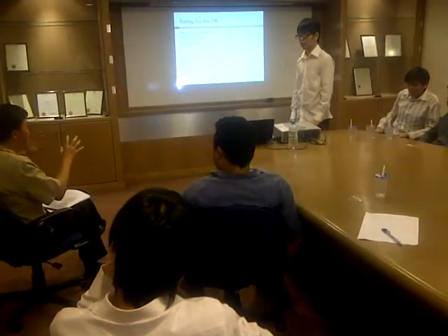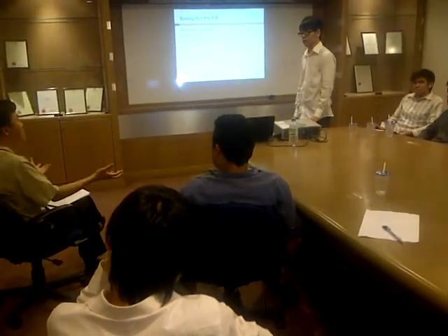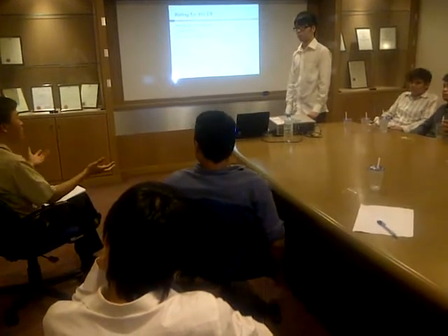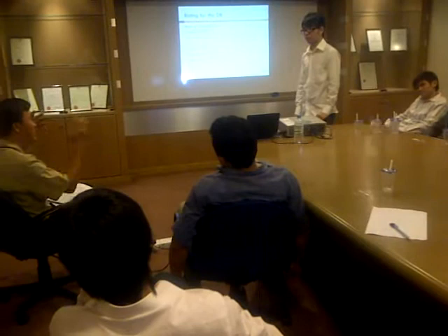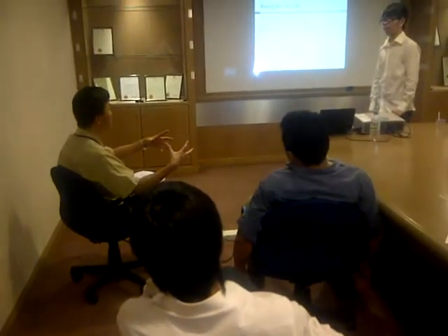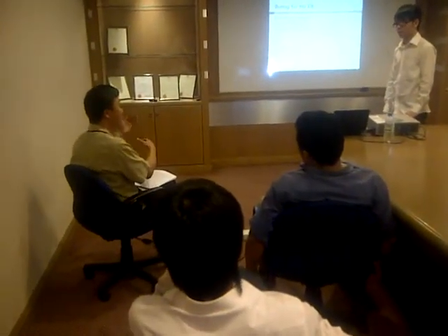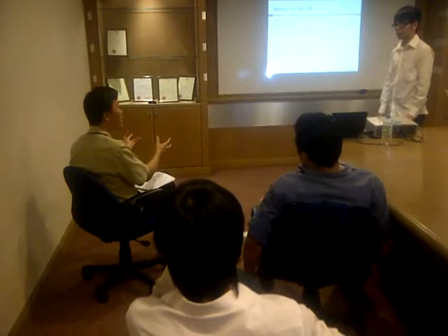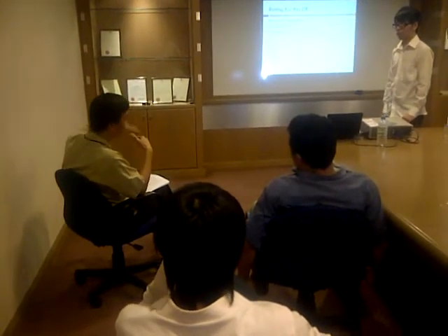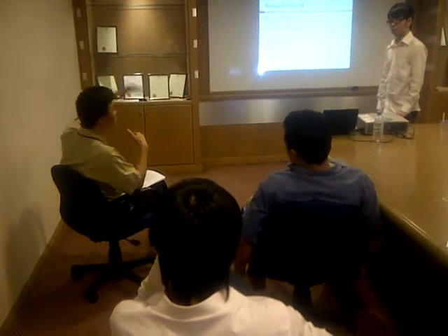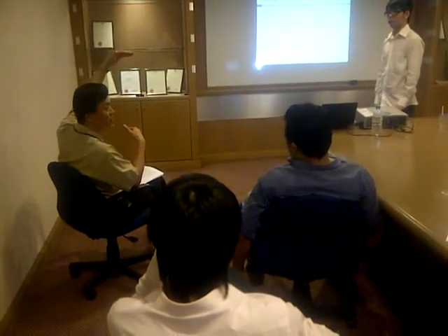Okay. You multiply the quantity of all the socket outlets with 250 watt. Let's say you have 100 socket outlets, I multiply by 250, it is going to be a big figure. If I assume 500 watt for the socket outlet and multiply by 100, the load is even higher. At the end, everything will go for very high load demand.